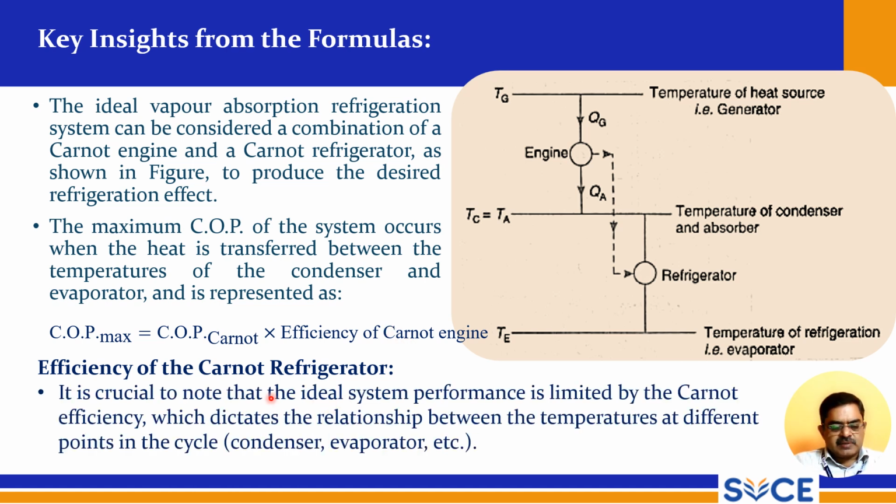It is crucial to note that the ideal system performance is limited by the Carnot engine efficiency, which dictates the relationship between the temperatures at different points in the cycle, that is condenser, evaporator, etc. So these points are considered, and the efficiency of the Carnot refrigerator is defined like this.